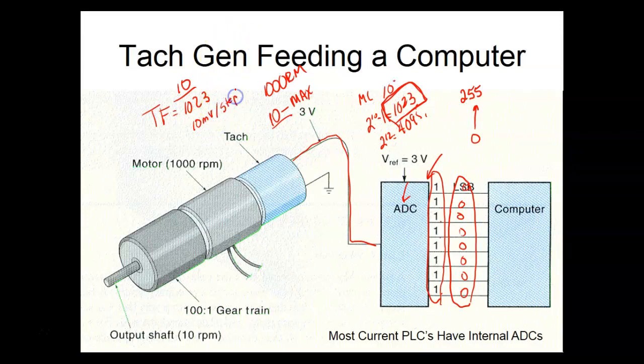Now the problem with this is that these steps can't go in between. So what we're saying is, if I put 9 millivolts in this thing, it wouldn't do a step. So an A to D converter is going to look at steps. So on this, each step would be, since it's 9.7, 10 millivolts per step. That makes sense?